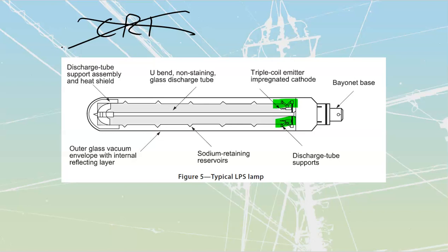What they do have is a very, very short restrike time, and a very high efficacy, the amount of lumens that I'm able to get compared to my watts. These were going to have an efficacy sitting up there in like the 200 range, which used to be incredible. We are getting way higher these days with LED lighting, but that used to be absolutely incredible.